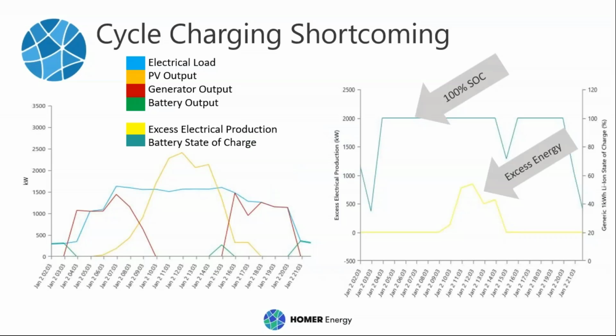So about HOMER Predictive, here HOMER Predictive dispatches batteries most intelligently using a 48-hour look-ahead period. And so with HOMER Predictive, we're actually addressing maybe a shortcoming of other dispatch strategies which have no foresight capabilities. So in the other dispatch strategies, the operational decisions are made without any knowledge or forecasting of the future. And with the technology that's out there today getting better and better, you have more accurate solar forecasting and load prediction. So HOMER Predictive mimics these smart controller technologies.